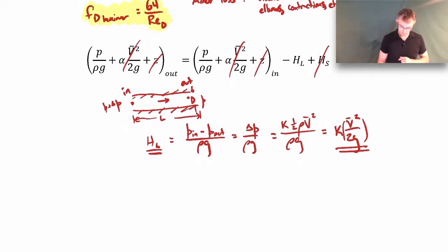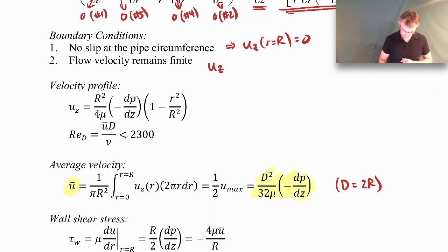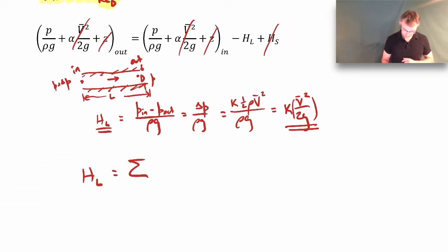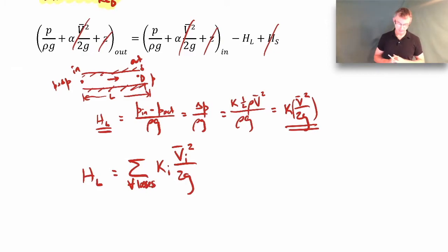And if we do that, then our head loss term, in general, will be the sum of all the loss coefficients times the velocity heads where those losses occur. So this is for all losses. This symbol here, this V shape with a bar through it, is not a volume, it means for all.